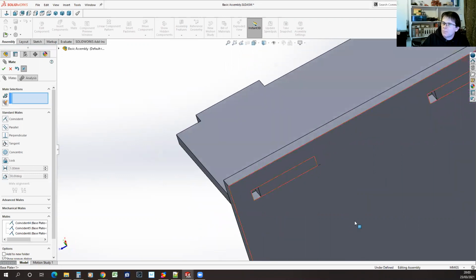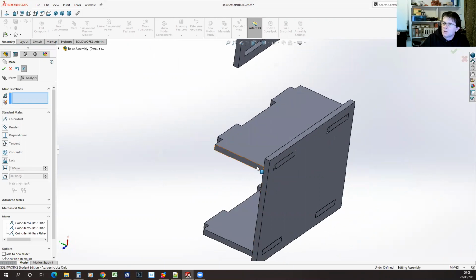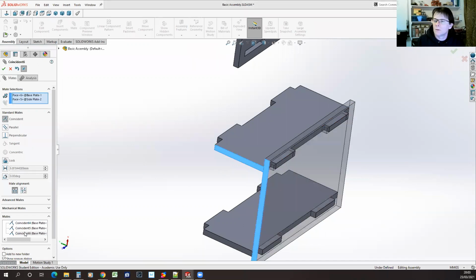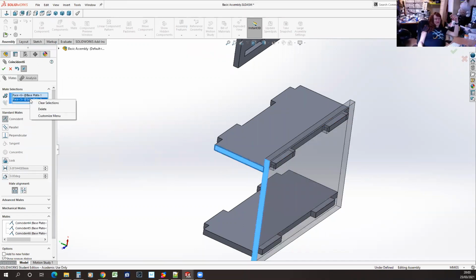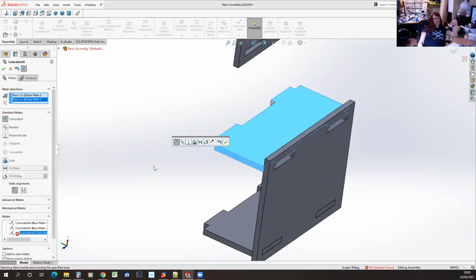Notice that my slots don't line up, because what I did was I aligned the edges, which in reality is not how your part holds together. Your part holds together by the slots. I was going to say, there's an easier way to get the part in the right orientation from the get-go. Just control drag it in the assembly, because you'll just pull a copy off. Control drag the existing part to duplicate it. Exactly. And it'll come off in the same orientation.